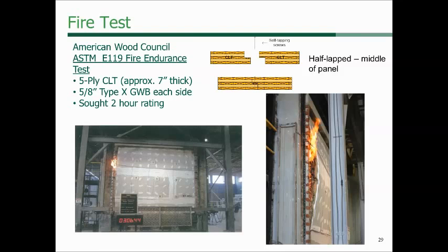This actually was one that had a 5-ply cross-laminated timber, manufactured per the APA PRG 320, and this test was an ASTM E119 fire endurance test. It has 5 layers of cross-laminated timber and then 5/8 type X drywall on each side, and we sought to have 2 hours of fire resistance rating, but it resulted in 3 hours and 6 minutes of fire resistance rating.